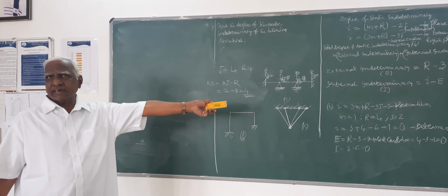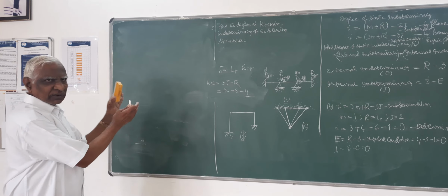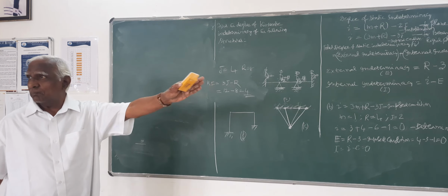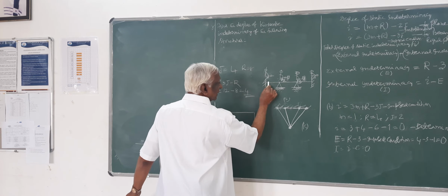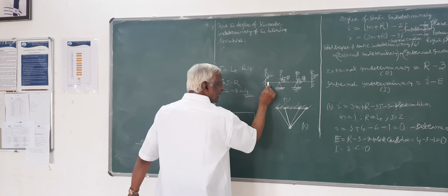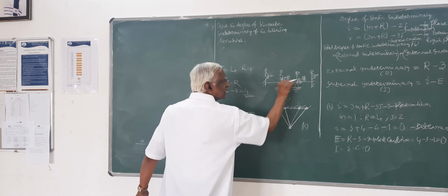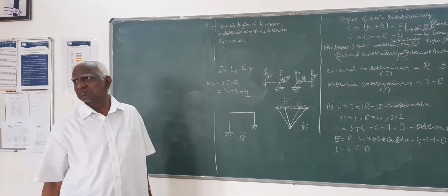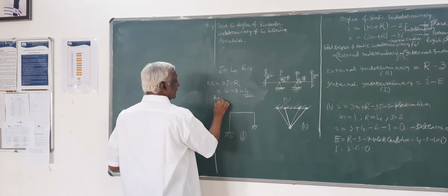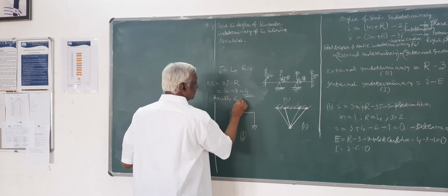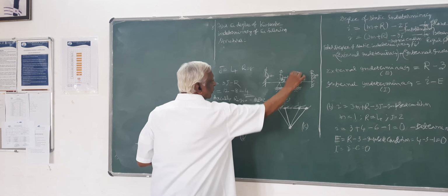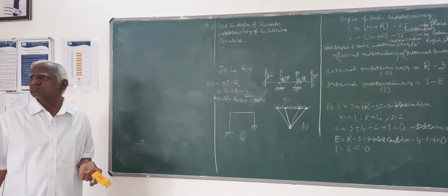Here, there cannot be any displacement, because if the left moves, the right also has to move by the same. Then, if you go on moving, this rigid body motion cannot occur, this cannot move. Likewise, this also cannot move. So only 2. If it is axially rigid, kinematic indeterminacy is 2. That's only rotation at those points.